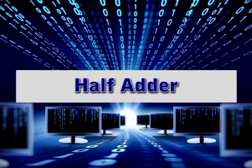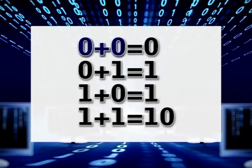First one is the half adder. Digital computers perform a variety of information processing tasks. Among the basic functions encountered are arithmetic functions. The most basic arithmetic operation is the addition of two binary digits. We have basically four possible elementary operations of addition, and they are, as you can see in the diagram, 0 plus 0 is equal to 0, 0 plus 1 is equal to 1, 1 plus 0 is equal to 1, and 1 plus 1 is equal to 10.